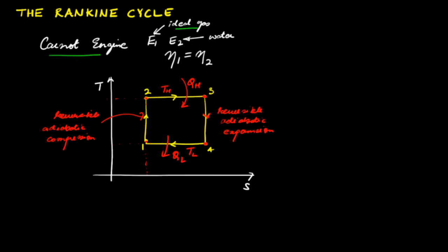So this heat engine gains entropy QH over TH from the step from 2 to 3, that is during heat transfer from high temperature. But then during the process of heat rejection, it dumps this amount of entropy to a low temperature reservoir, and the net effect is that once the cycle is complete, there is no change in the entropy because entropy change for the cycle is 0.